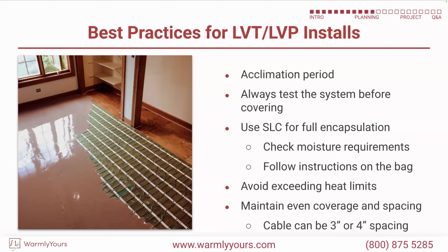What are some other things you want to look for here, Mary? Oh, acclimation period for your LVT or LVP product. That's always important, especially in the extreme summer or winter months. If you get a delivery and they leave it out in your garage for a week and then you bring it in the house, you want to let that flooring just kind of come up to room temperature before you begin.